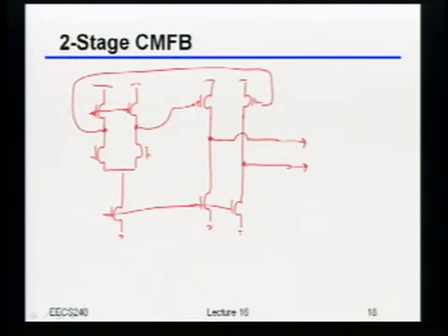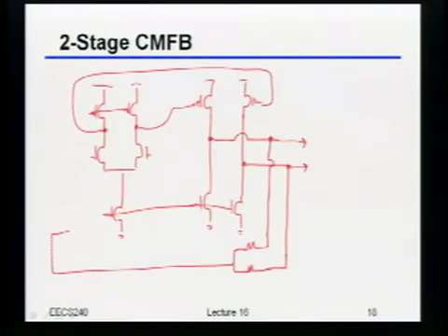So why don't I just use that one final output, sense the common mode over there, and tie the feedback loop through that. As an example, I'll draw resistive feedback here just because I'm lazy, but you might actually do this with capacitive feedback. So let's say I do something like that. Okay? So this is some desired nominal common mode voltage.